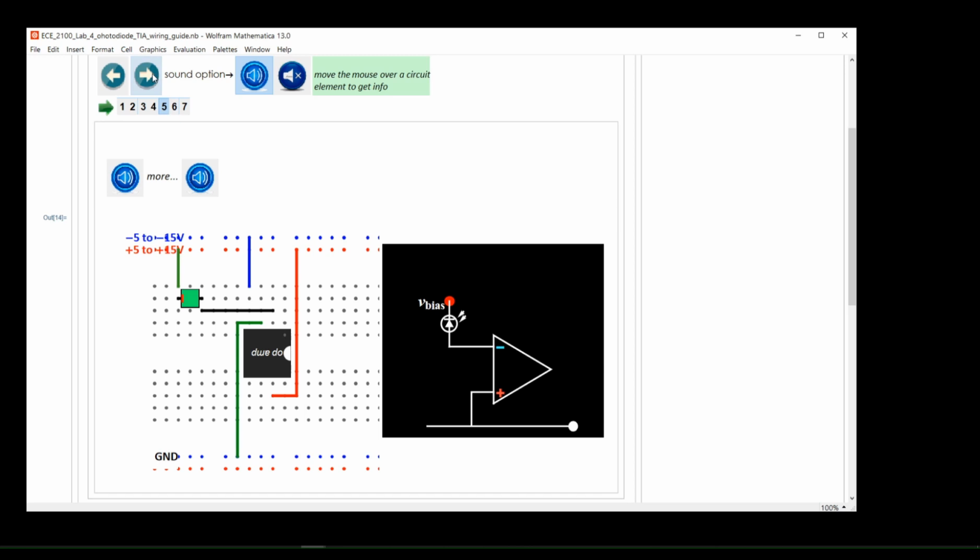If it were forward biased, there would be a large current that would swamp the photocurrent, which is the current of the light signal. To detect a minuscule photocurrent within a torrential forward bias current would be like listening for someone's whisper in a big noisy stadium. In addition, the reverse bias affects a strong internal electric field that increases the photocurrent collection efficiency. Hence, one should check the photodiode polarity and wire it carefully.